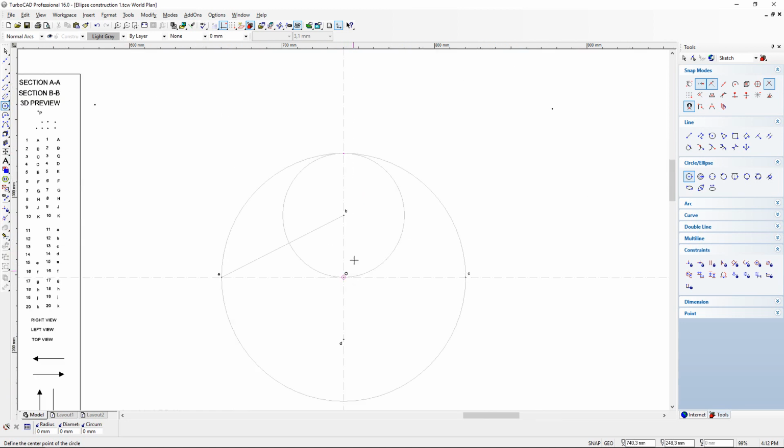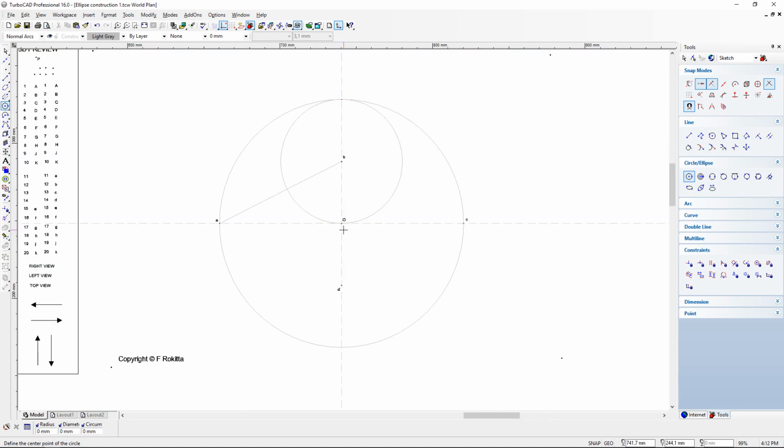Now this looks a little bit cluttered on my page, and in drawings we want to draw as professional and neat as possible. Therefore I'm going to do some housekeeping, is what we call it at school. So I'm going to click here on this tool. We call it the split entities tool on the far left of your toolbar. There are many other options which we'll maybe discuss during the course of this drawing or other drawings, but we need the split entity tool for now.